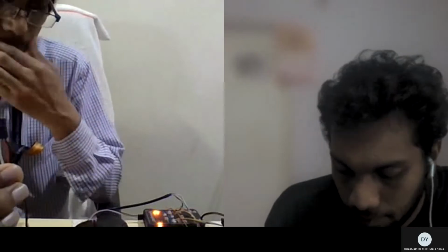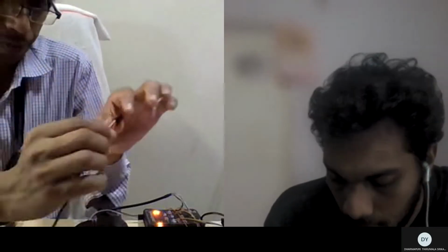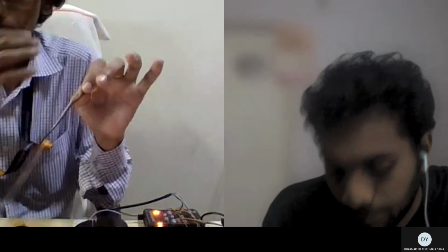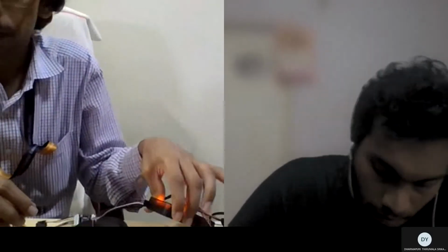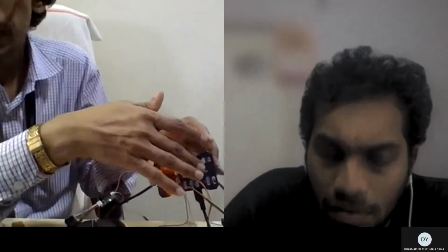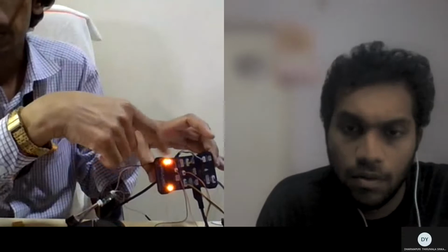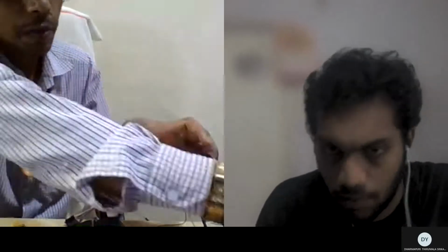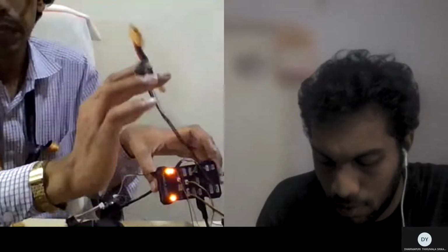Okay, 5 volt supply. So sometimes what happens, when you are connecting all the speed controllers with the flight controller, the rail where you are connecting requires power. Mostly you have it powered already. When you have a power module, this will get powered, no doubt, because the power module will be connected with the flight controller.